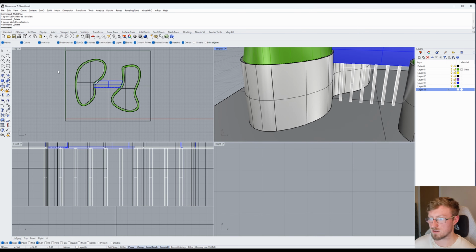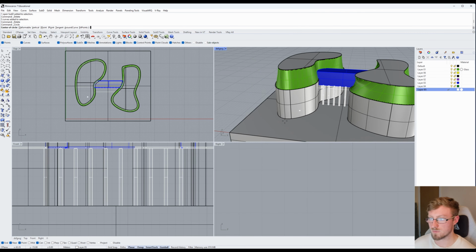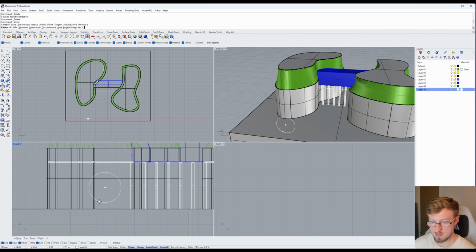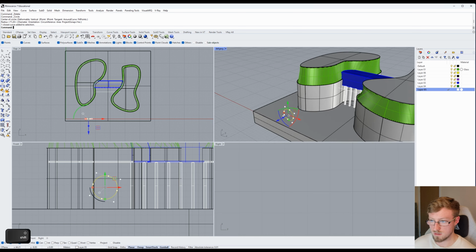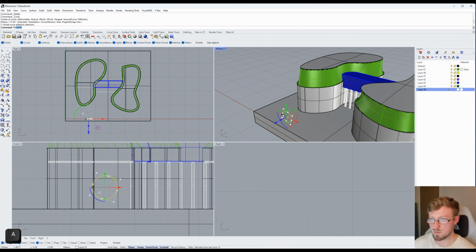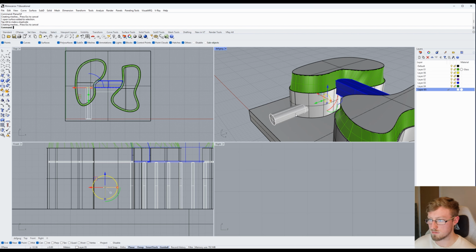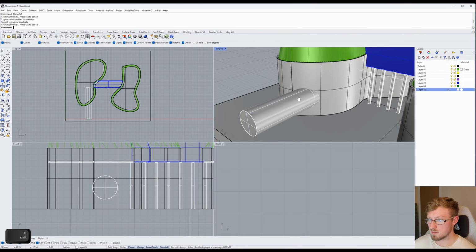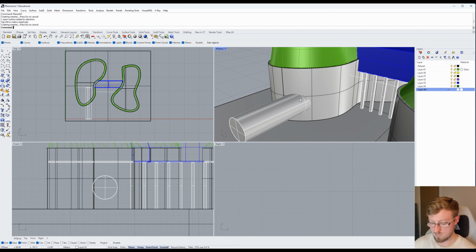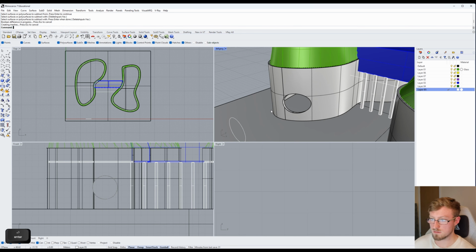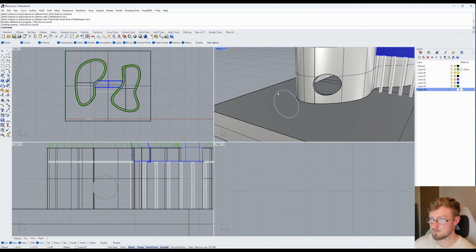Yeah, so I wanted to make a hole then right through this. I could go through here, just do this, there. I could create a solid because this is also a solid, and drag it right through. And Boolean difference, I'll subtract from that, that's going to be the cutting. I'll create a hole through.